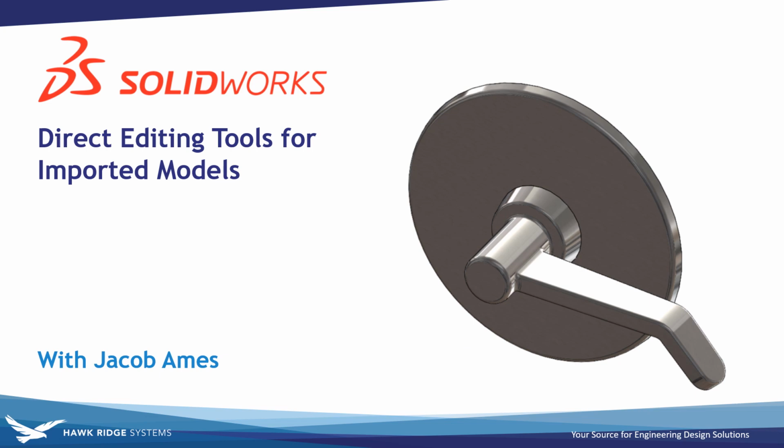The term direct editing is used in SOLIDWORKS to describe the process of making changes to a design by modifying the geometry directly through moving faces, splitting solid bodies, and a number of other techniques as opposed to editing existing features. In this video, we'll be covering some of the most popular direct editing tools and workflows to get you up and running with your imported models.